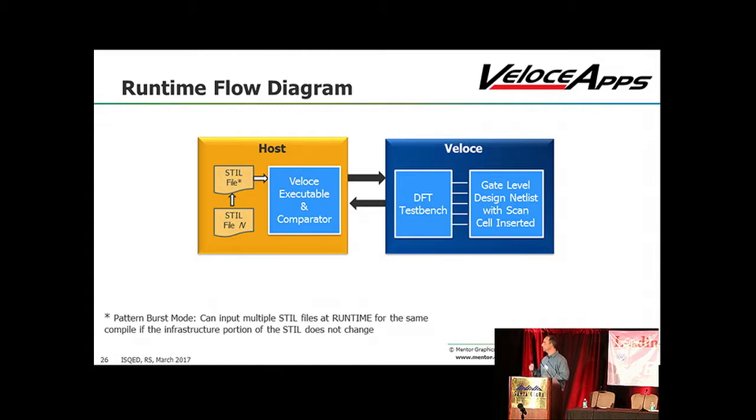Now, if you've got, let's say, 2 patterns that have different pin headers, then just like on the tester, you have to recompile. It would be a test insertion on the tester where you have to load new timing, new wave sets, things like that. Same exact thing on the emulator. You can't burst them together, which is actually nice because now you're verifying your test program, making sure you don't make that mistake on the tester. You've got a pattern that just doesn't compile.